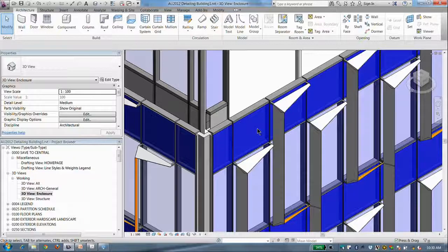But the curtain wall mechanism allows us to very easily hang all of these fins off of the building in the right location. We just basically create a curtain wall, grid it up. Because the fins are 2 stories high, the grid for the fins is every other floor, and horizontally it is the same width, 1,400 millimeters and 1,500 millimeters on the adjacent sides. So it's relatively easy to work with the Revit curtain wall to hang these fins off of this.